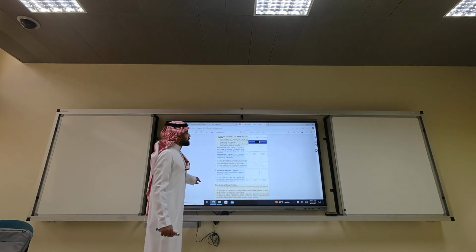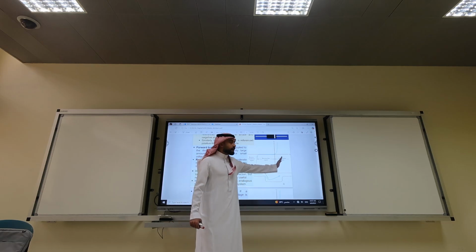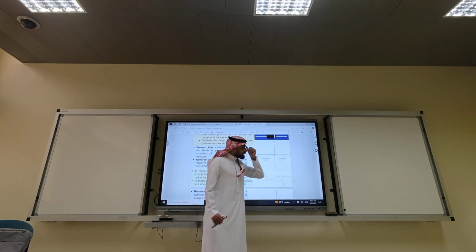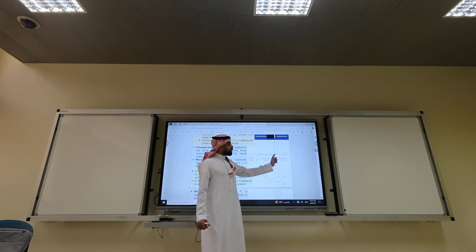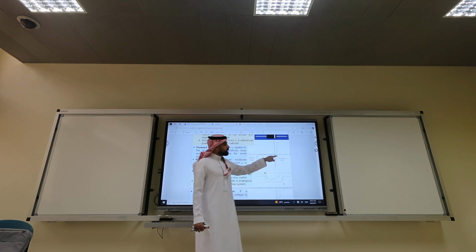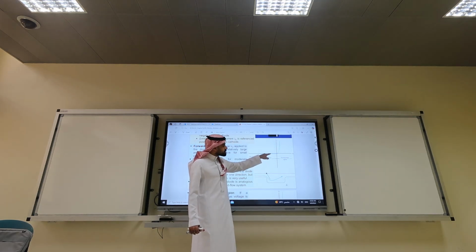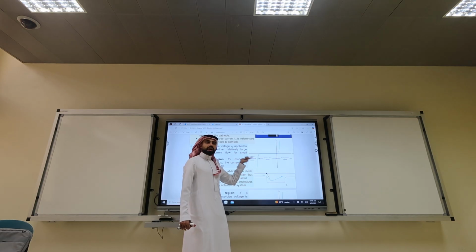Last time we talked about the regions of operation, okay? So how many regions of operation do we have? 3 regions: forward bias, reverse bias, and breakdown. Forward bias, if you apply just a little bit above 0.7 volt, you will allow current to flow. So if you apply 1 volt, whatever current the system allows, it will flow. If you apply a voltage down to minus 10 volt, it will block the current. Only a small current will leak. If you apply a big negative voltage, we will break down and the current will flow, okay?